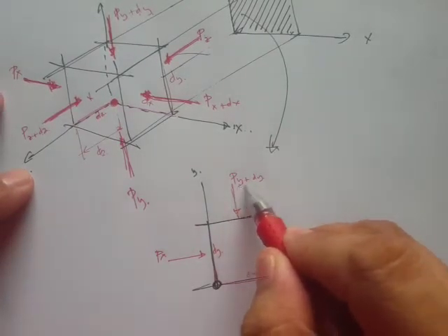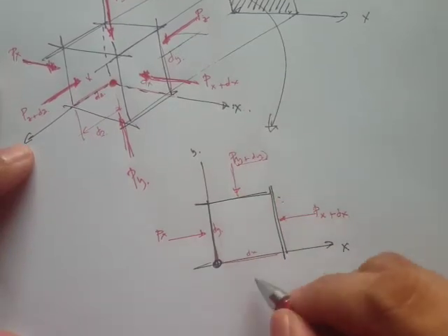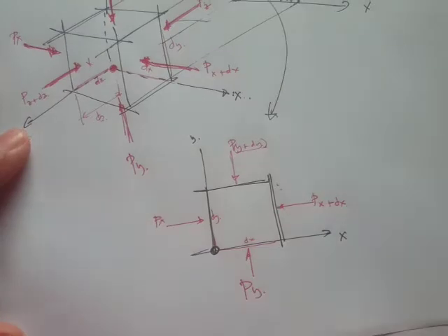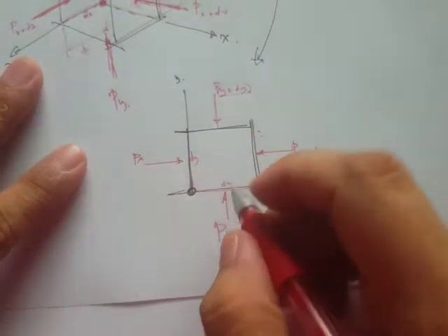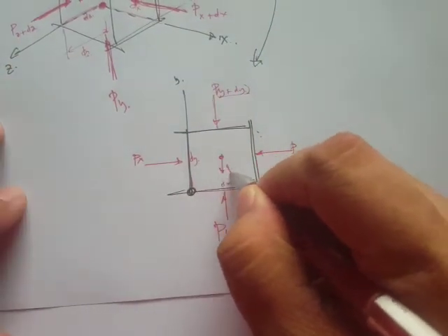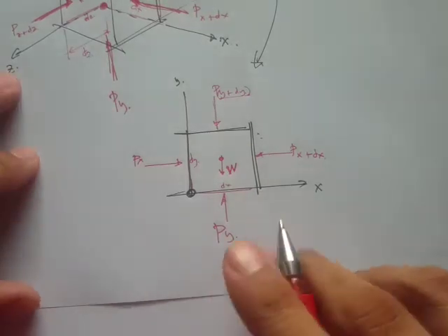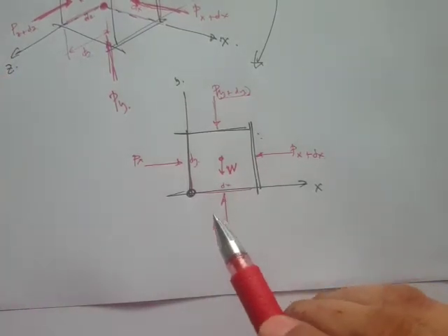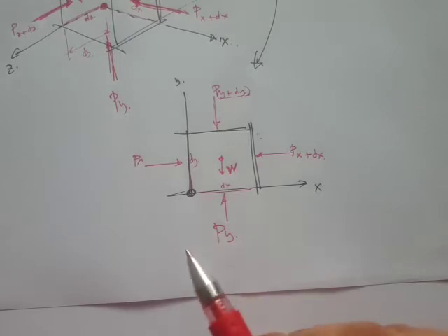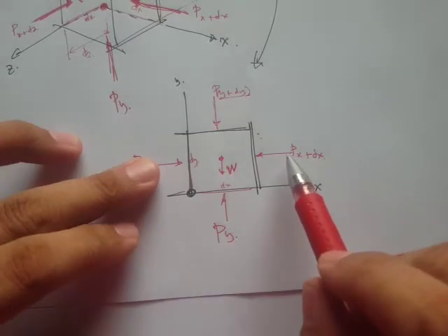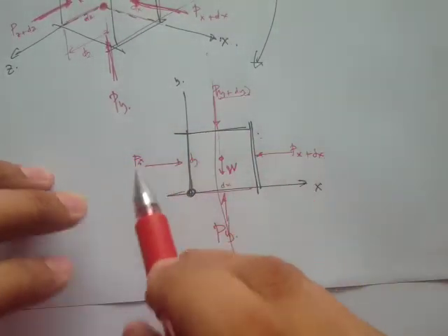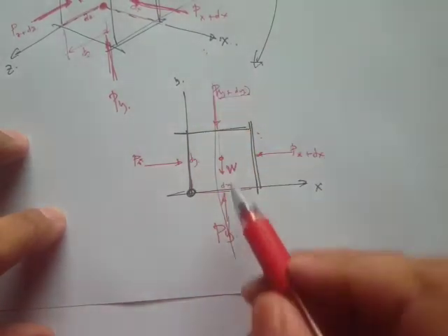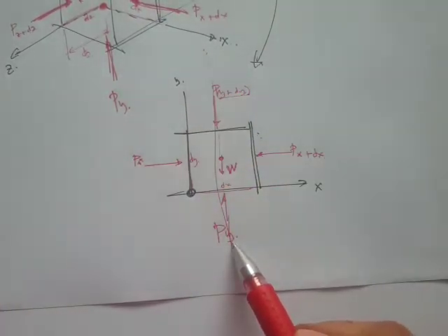By the way, this is written as subscript, and here we have b sub y. Okay, so along the y direction, there's still also the weight of the fluid. So that's weight. Since it's not moving at all, at this equilibrium condition, we'll see that there's going to be an unbalanced force along the y-axis only, along the vertical axis, because here it will just cancel out because they're balanced, but along the y, there's going to be a difference.